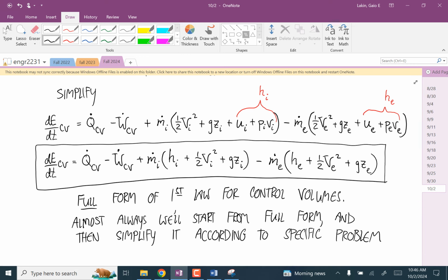Okay. So if anyone asks you what enthalpy is, just go through this derivation. That's all enthalpy is: a mathematical simplification of a bunch of stuff that popped out of this derivation. And that's why enthalpy changes on those tables, because it depends on P and v. Yeah, that v is specific volume. Yep.